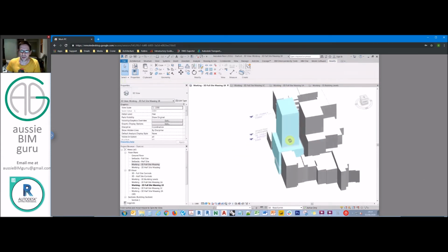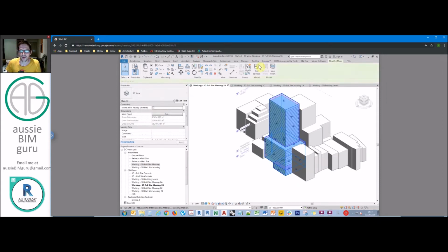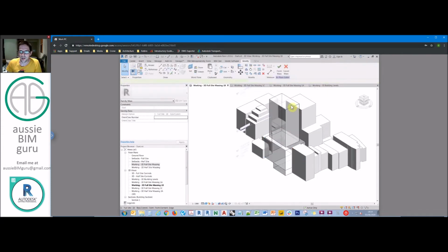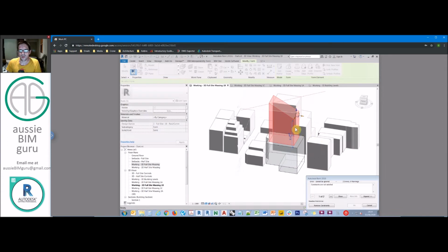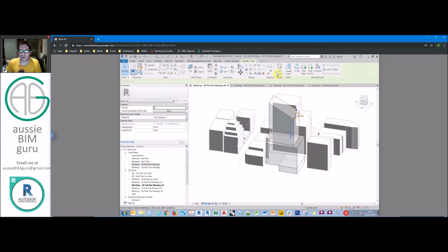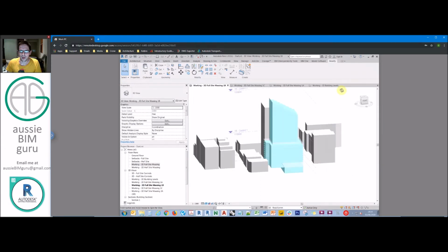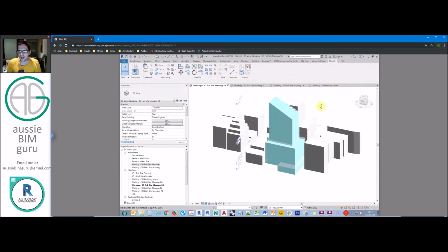And there you go, that's as simple as it is to, I guess, set up a building mass option. So really, the plan and control mass can be just copied and manipulated to become a building mass. Obviously, you can get more detailed as well with massing. You can actually take edges and push them down to create chamfered forms. In this case, I won't, but that's possible as well. And your building mass floors will obviously respond to that change as well. So that's the great thing about mass floors, they follow your geometry. But we're just going to stick with a more regular mass for now.